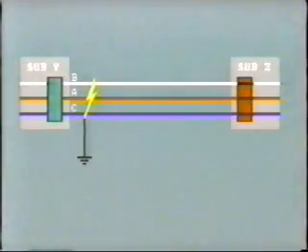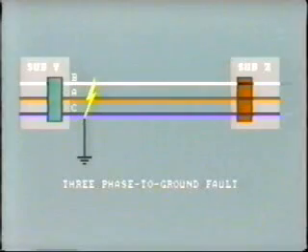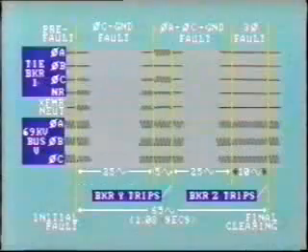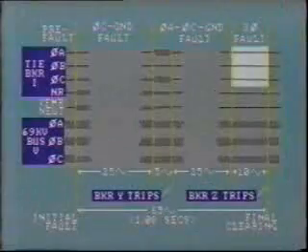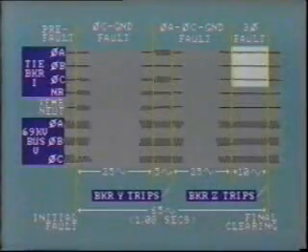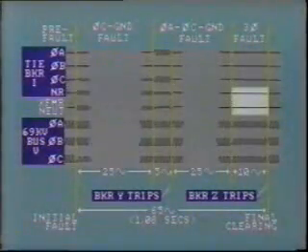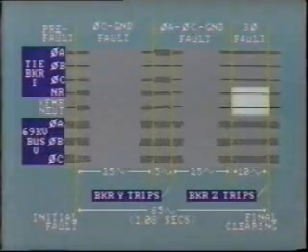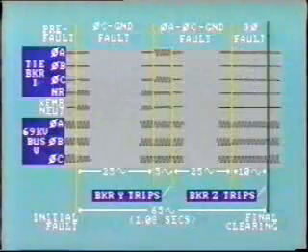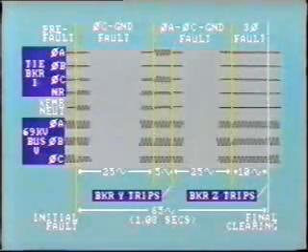But all 3 open conductors are now in contact with ground, resulting in a three-phase-to-ground fault. For the next 10 cycles, we have a balanced three-phase fault. You can see this from the three fault currents in the tiebreaker and the fact that neutral and residual currents are now zero. Breaker Z at the other end of the faulted line now trips to completely clear the fault.